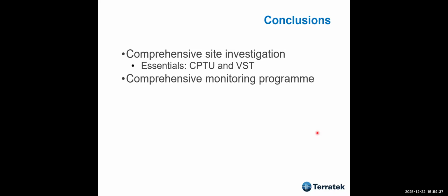So the conclusion is we must have a very comprehensive site investigation. The essentials are CPTU and VST. I don't like some recommendations of the ASTM. I think the ASTM standard is wrong. VST should be standardized. The vane should be standardized. I don't like the possibility of using many different types of vanes. No, I don't like that. We need a comprehensive monitoring program.